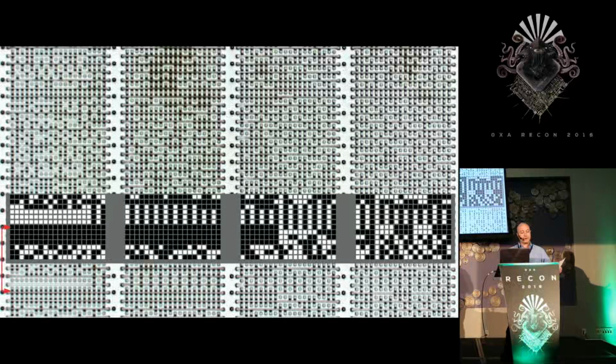In this image, I overlaid the extracted bottom 13 rows of bits over the photograph. You can see some visual patterns within the bits, and this is a really good indication that the ROM is probably not encrypted or heavily scrambled.